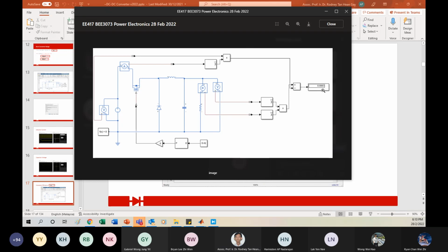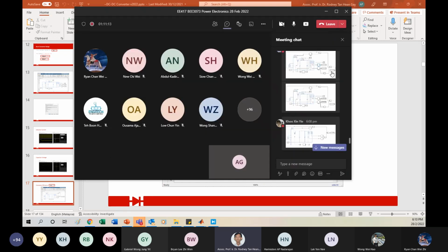89. Yeah. So just now I just demoed. If you use the Schottky diode, you can increase the efficiency without paying any extra money or changing the design. See, that's why I say this type of knowledge is very, very important.